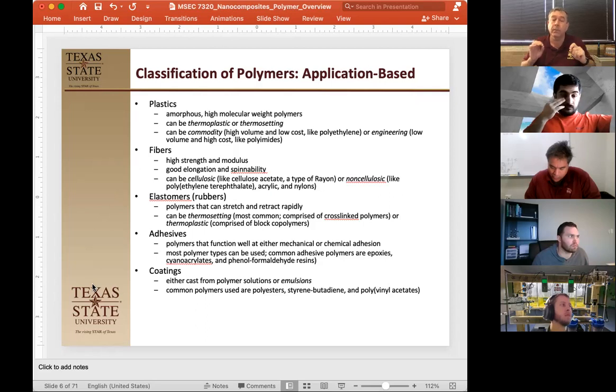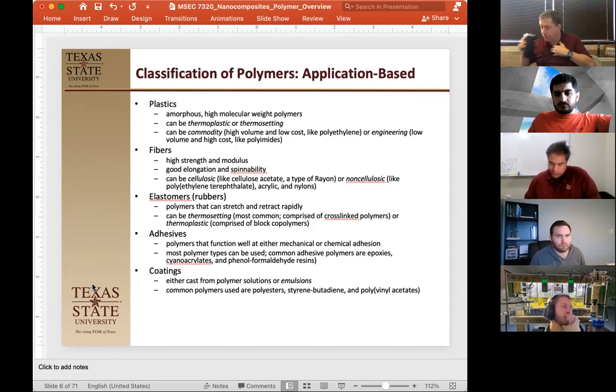However, there are thermoplastic elastomers. These tend to be things like polyurethanes, where you can actually have polyurethane pellets that are elastic, and you can melt them and form them into films, and they still have their elasticity. And that's because of the intramolecular interactions that allow them to spring back. So there's two different processes there. They can either be cross-linked or have intermolecular forces. But the key thing is that they can come back once they're deformed.